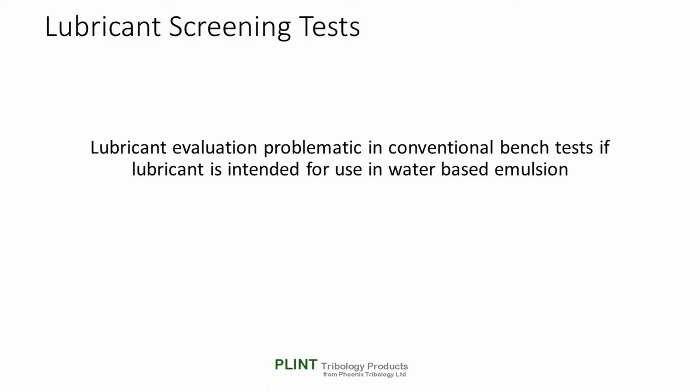For many years, a number of basic continuous sliding lubricant screening tests have been used, each claiming to provide useful data, but in reality, data of limited scope. The machines are all thermally self-regulating continuous energy pulse devices in which contact temperature is both uncontrolled and cannot be measured.